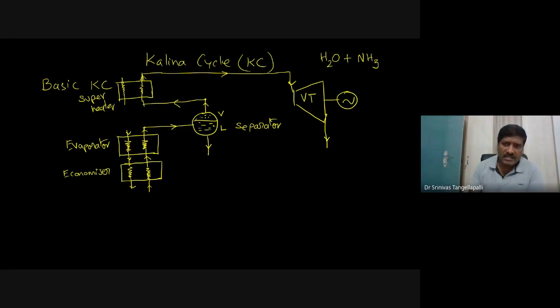So straight away, this large quantity of ammonia we can't condense in a water cooled condenser or air cooled condenser. That's why it has to be diluted by adding water. Since we already have the liquid here with a concentration almost close to water, you may call this the weak solution. So the corresponding concentration you may call the weak solution concentration. XWS is the weak solution concentration.